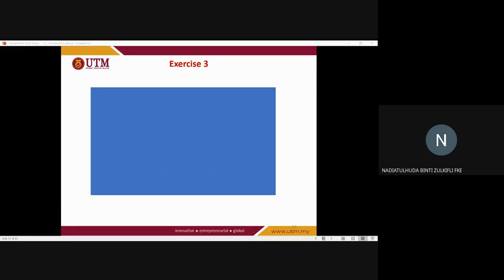Ideal situation. It's when the system does not add noise. So there's no added noise in the system. That's why SNR in is equal to SNR out. Not only noise, but your power also is the same. It does not experience loss, or the losses are compensated to the same level as the input signal. So SI is basically the same as S out. So this is when we have F equal to 1.